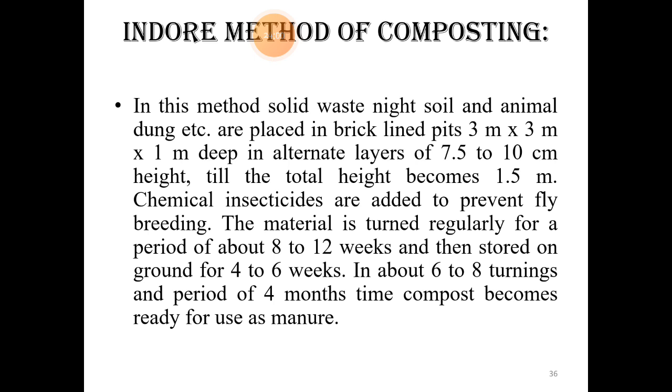The same method of trenching of compost technique is also used for the indoor method of compost. In this method, a brick-lined pit of 3 meters long, 3 meters wide, 1 meter depth is made.